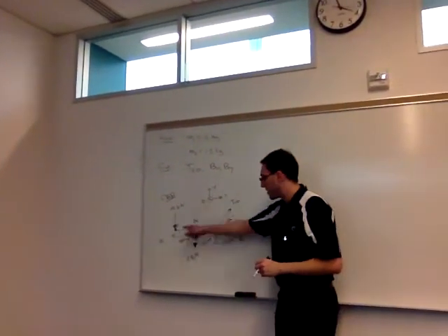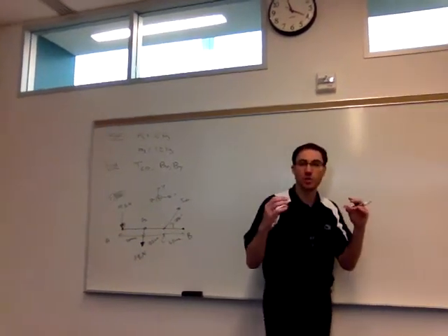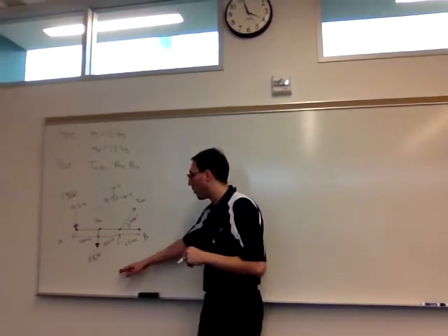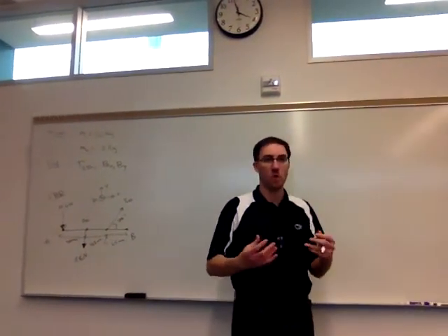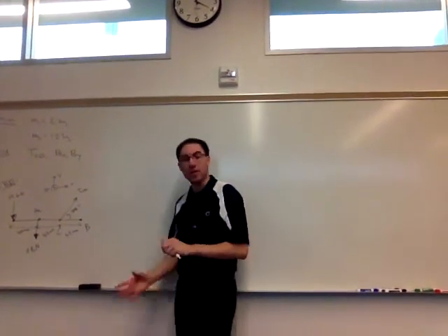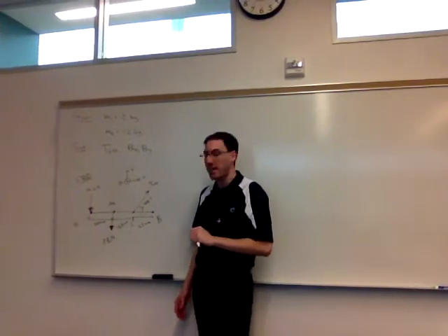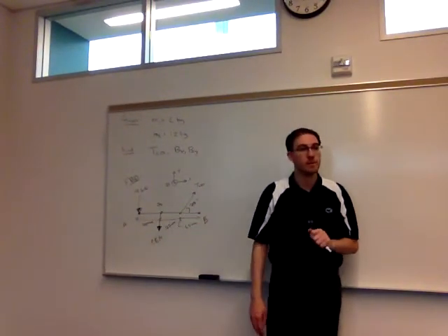All right, so again, it's not even twice the mass of this. When we're talking about actual structural members in, like, a bridge, the weights of the members themselves might be like 1% of the force that they're holding up of cars or things like that. So in those cases, if it's like 1%, we usually neglect it for simplicity in our analysis. Here, it's about 50%, so we don't want to neglect it.